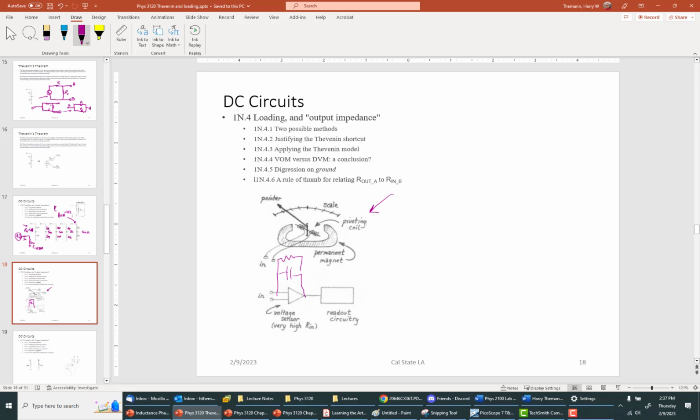It charges the capacitor, and then it measures the time constant, which we're going to do hopefully today. I'm going to show you how to do that in a few minutes. It measures the time constant of that RC circuit. And not only that, it measures the voltages and the change over the RC, because the RC is fixed by the value. So it has some way of counting and converting the time into a voltage reading.